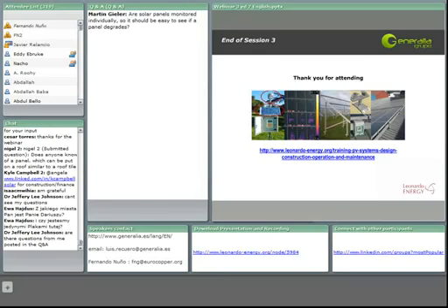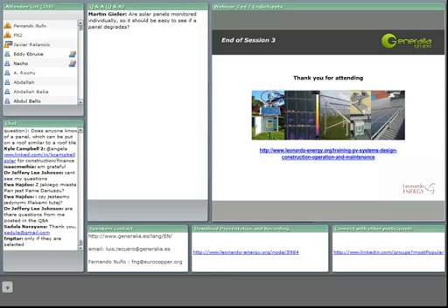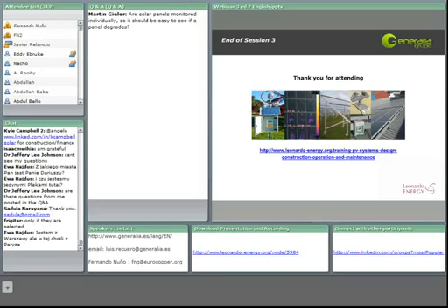Anyway, if the panels are not reducing their performance drastically, we can consider that with a typical tolerance of 3%, it is not important to get less performance from one of the panels. If we find that the production from a row or from a whole sun tracker or a whole panel area is lower than it should be, we can apply one of the practices that we saw during webinar 2, like for example the thermal study of the panels in the area that we detect is producing lower than it should be.